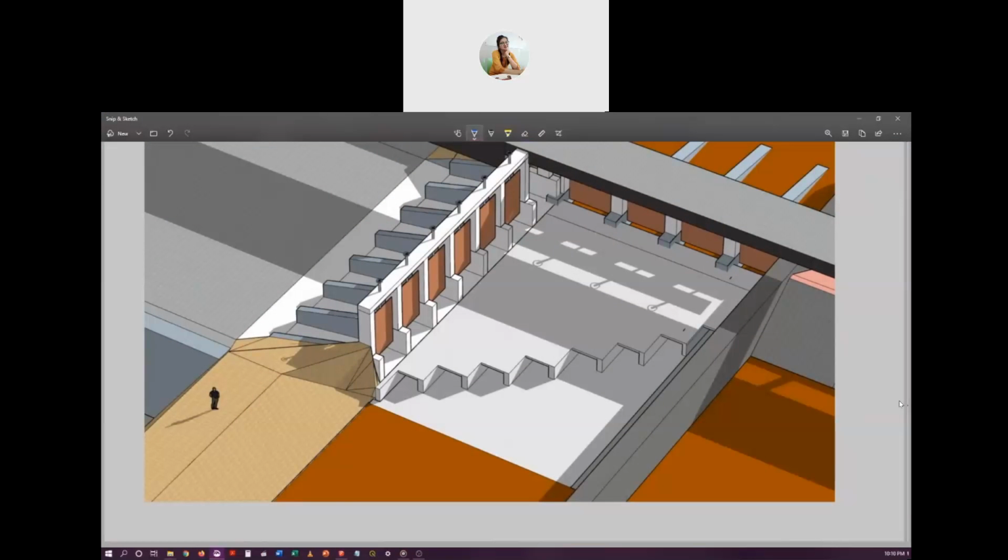when water goes into these gateways, they have a velocity component like this. And if we had made all these tunnels of the same length, then because the velocity is in this direction, water will not enter all these tunnels and will flow past perpendicularly.